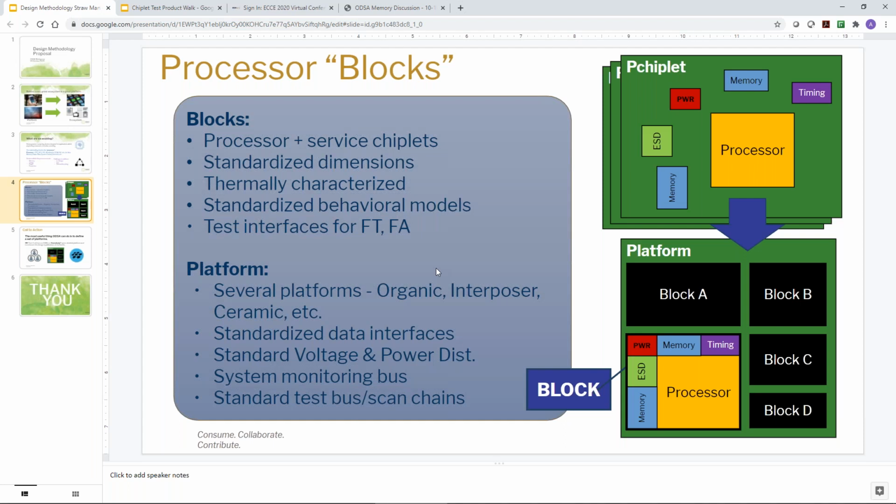Okay. To your point, Elko, for example, if you would have all those blocks on the top right with the same common interface, for example the BoW interface, and every one of them had a certain rate of BoW interface, then it would be easy to integrate them. And of course, they would have maybe multiple options of die-to-die connection in terms of package level wiring.